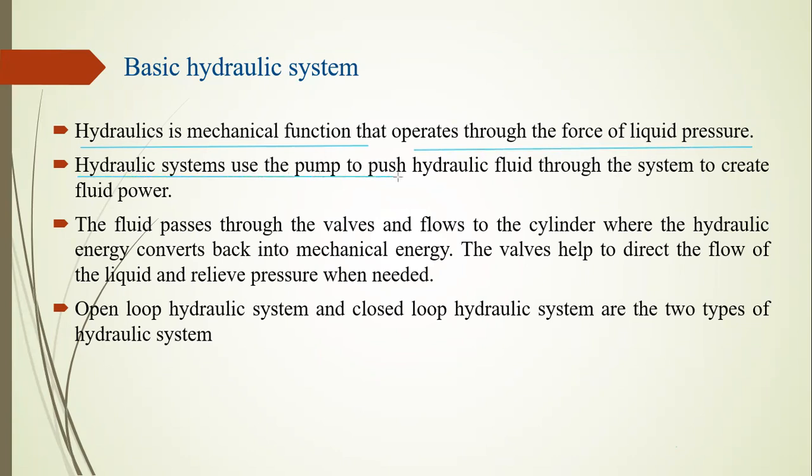A hydraulic system uses a pump to push hydraulic fluid through the system to create fluid power. Hydraulic pumps pump the fluid from one place to another, that is, from the reservoir tank to the hydraulic line, creating a higher pressure, and this pressure creates useful work. The fluid passes through the valve and flows into the cylinder, where the hydraulic energy converts back into mechanical energy. First, we apply mechanical energy.